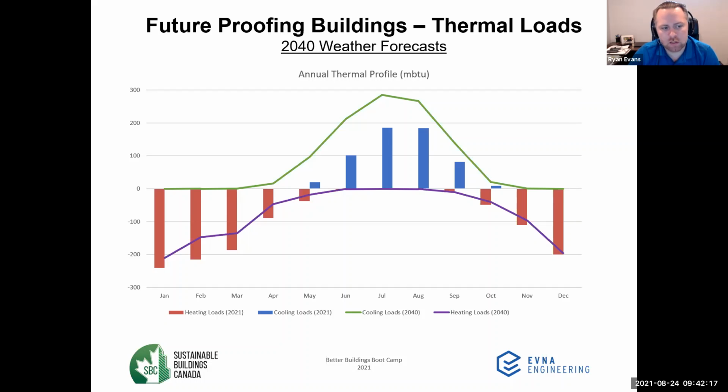So we're seeing that it's getting a little bit warmer on the heating side. Hence, it's not going to be as cold during the wintertime. However, we are seeing a much bigger uptick in the cooling season. So that means summers are going to get really hot. So this is something that we want to take into consideration, that buildings being designed today without air conditioning is really a big no-no, because that's putting the health and comfort of the occupants at a significant risk. Maybe not today, but definitely in about 20 years from now.